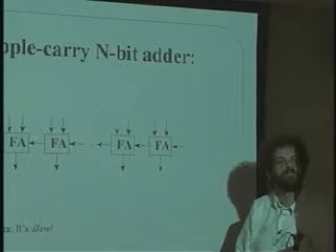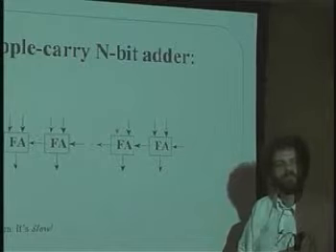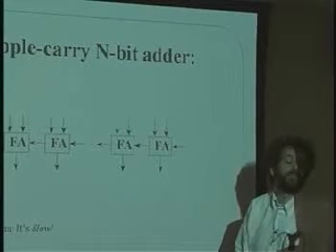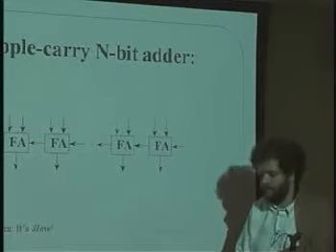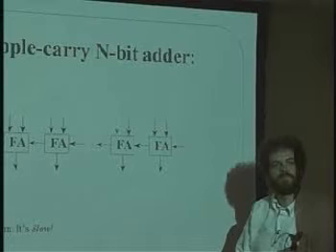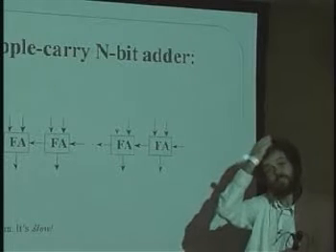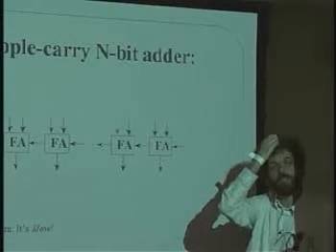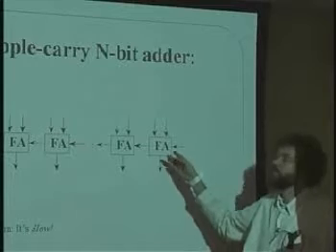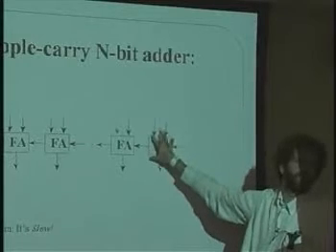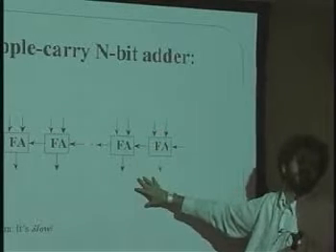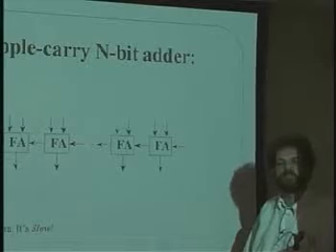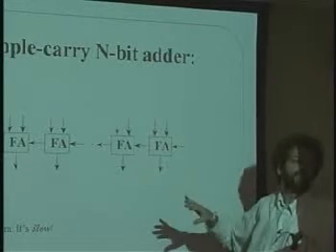But wouldn't you have to check all the way along the line anyway, in case there were, say, in the n-1 bit, 2 ones? Sure. Absolutely. There could be a whole bunch of zeros on both ends and in the middle. So then the question is how do you know when you're done, right? And of course the safe thing to do is you wait for 32 times however long it takes one of these guys to work, and then you know that you're done. Or maybe you build some extravagant circuit to find out when you're done.